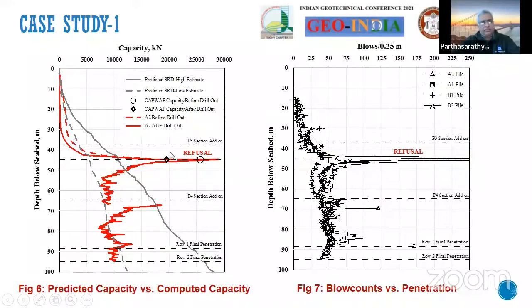These are some small decisions that you need to take. It's about 2 trials. They did the drill and drive techniques, but you need to have some conviction and courage to make the decision on site so that you don't spend extra time on the barge, because the barge time is too expensive in offshore conditions.